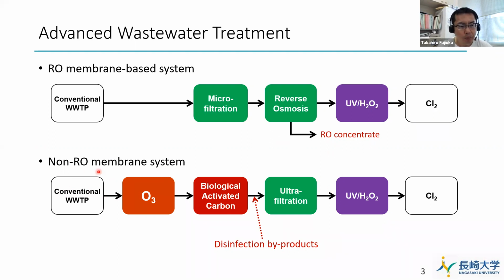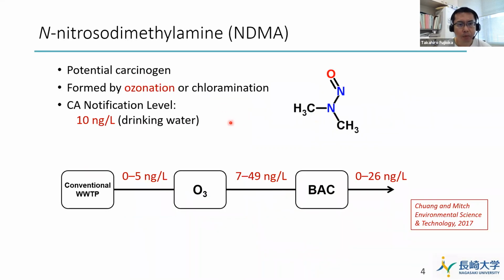So the non-RO membrane system is superior to the RO membrane-based system in terms of the disinfection performance, but there are big concerns in the formation of disinfection byproducts. Among them, there are two important ones. The first one is called NDMA. That's formed by ozonation or chloramination.